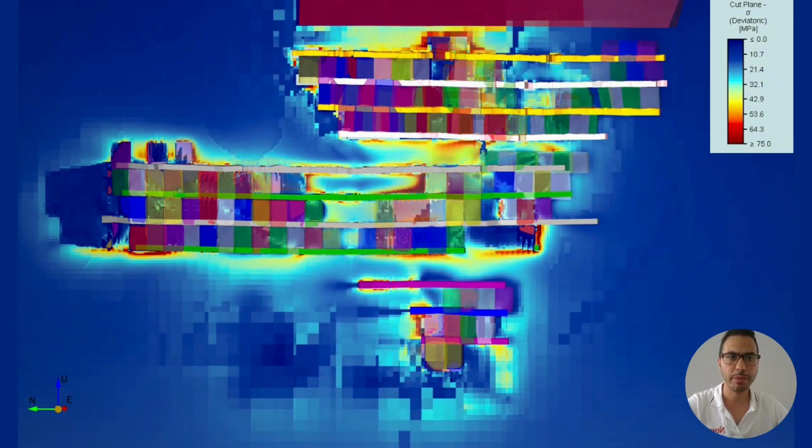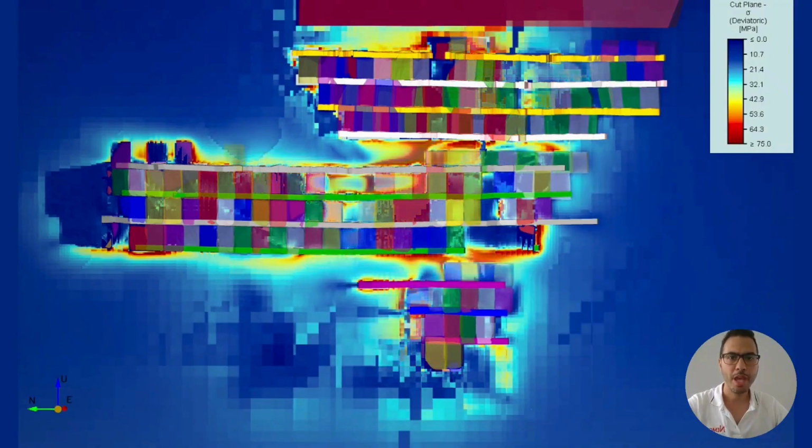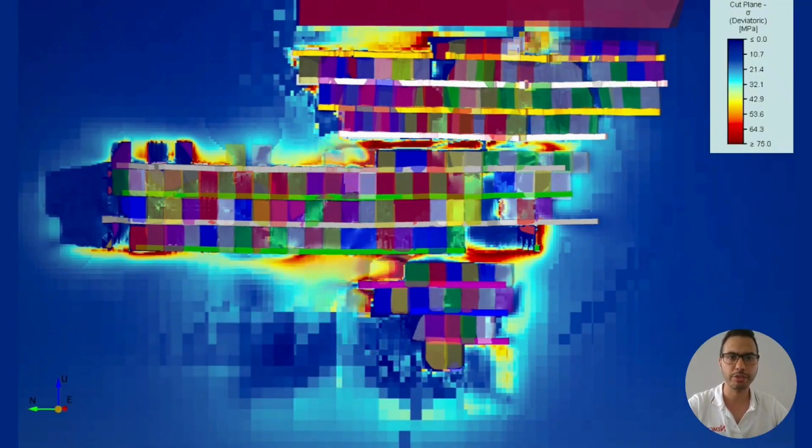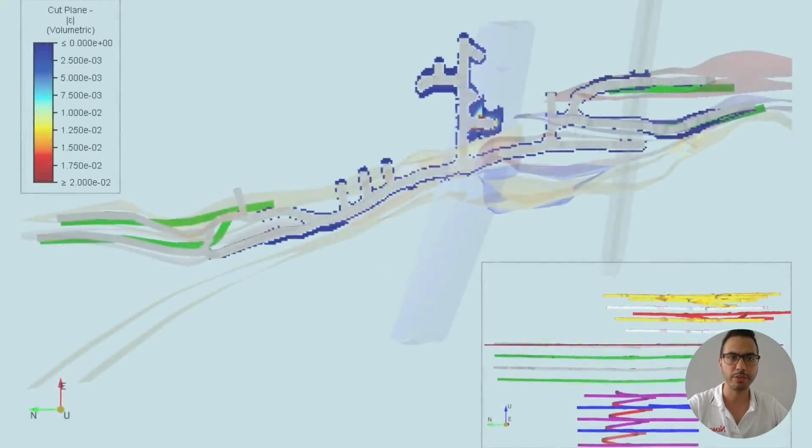If we switch the view to a longitudinal view and step the model through, we can notice that the abutment stresses around the stopes increase. This is to be expected as the major principal stress is said to be sub-perpendicular to the strike of the ore body. One interesting thing to note is that the brows in the final stages of a mining horizon are particularly critical and extra attention should be paid when it comes to ground support. Uppers at the final stage are also particularly critical and extra attention and focus should be paid to designing these and properly recovering this ore at risk.